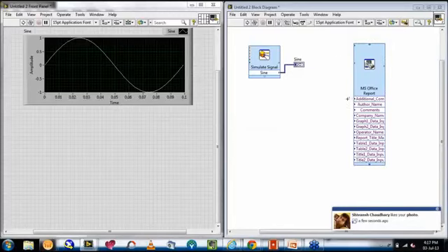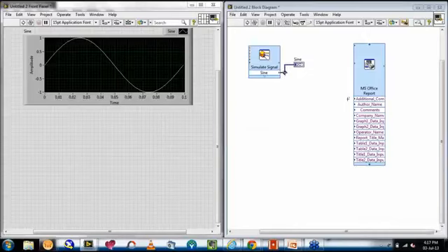All right. Let me start by showing you the wiring of the data to a particular graph which I want within my report. So I wired the sine data which is coming in to the graph 1 data input. Let me also wire this to the table 1 data input, because I want the value of each sample amplitude also within my report.